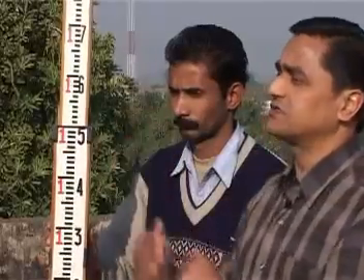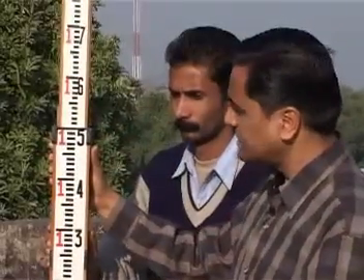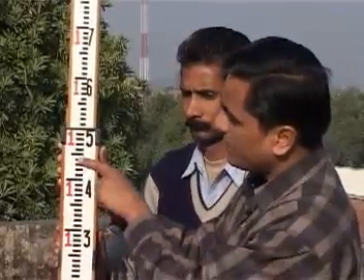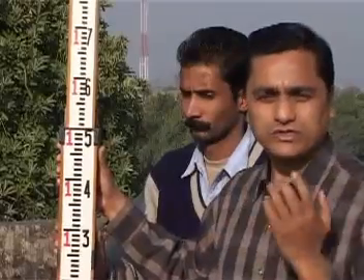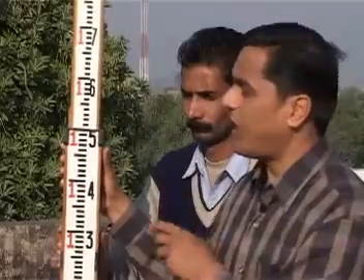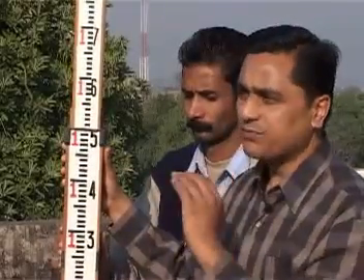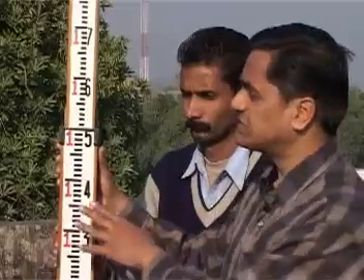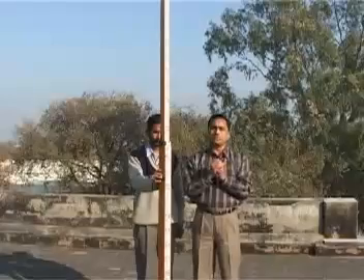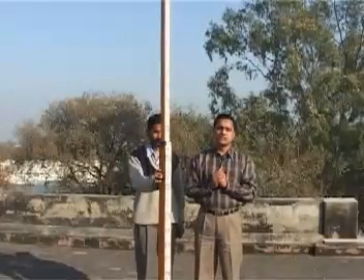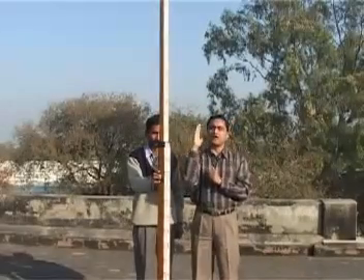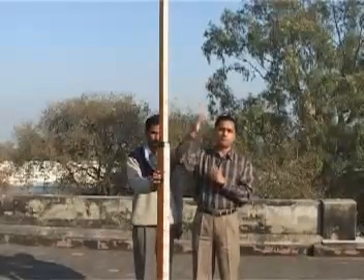We have also the folding staff. This is made of wood. Now in this case, if you observe closely, you can see the graduations here. Look at the graduations, you can see very well what is the least count of this. The least count in this case is half of a centimeter. Now it is important when you read it, sometimes you may see this staff inverted, because your telescope is producing an inverted image. So you have to be careful how to read this staff, from top to down. If the staff is seen erect, you read it from down to top.